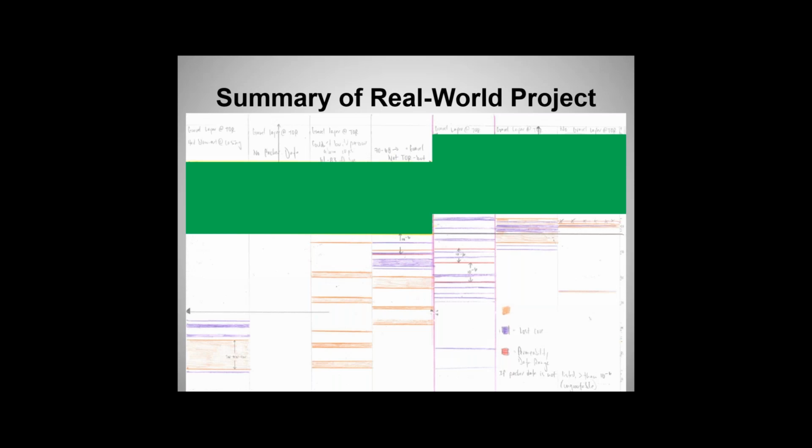But this is only half the step, because the next step is the cost benefit analysis that you always have to do. Are these two structures going to make 30 or 50 gallons a minute? And are they small diameter or large diameter? After you come up with what you can do, you still have to design it. If you estimate a price tag of $2 to $3 million for your grouting program for 50 gallons a minute, that doesn't make sense. It's not practical. Your contractor is just going to slap up some paneling and let it run down the shaft walls. It's more of a nuisance water at that point.